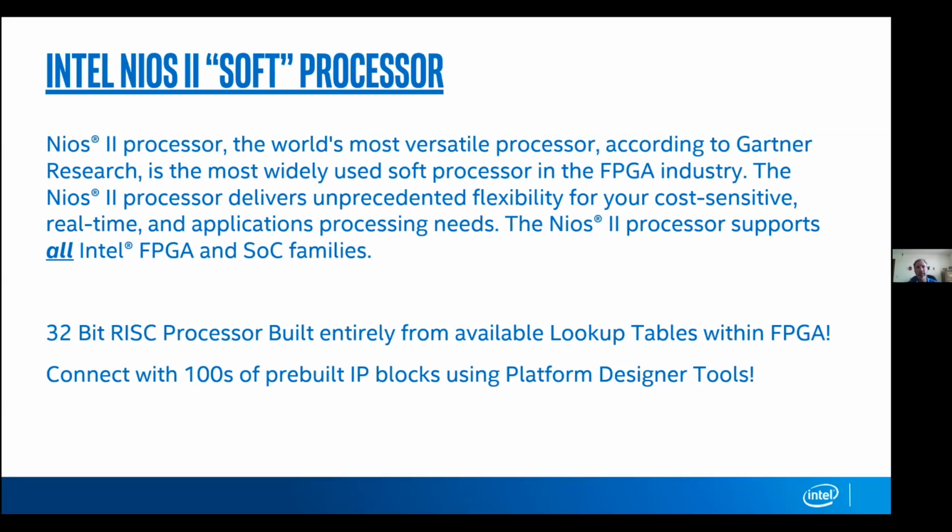If you're going to do something with a Linux operating system, you'd probably want to utilize our ARM-based product lines with our SoC products. But Nios is great for setting up different types of projects for students where they can have a processor and FPGA working in conjunction to solve problems. These Nios processors run anywhere from about 2,000 lookup tables to about 10,000. So they fit easily in any of our FPGA families, and we have lots of IP that you can connect together.